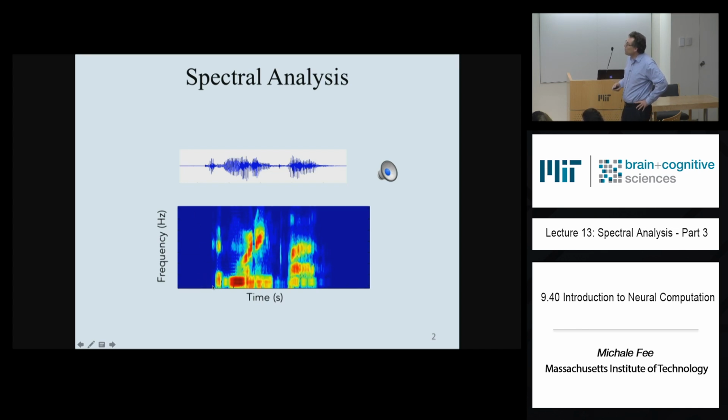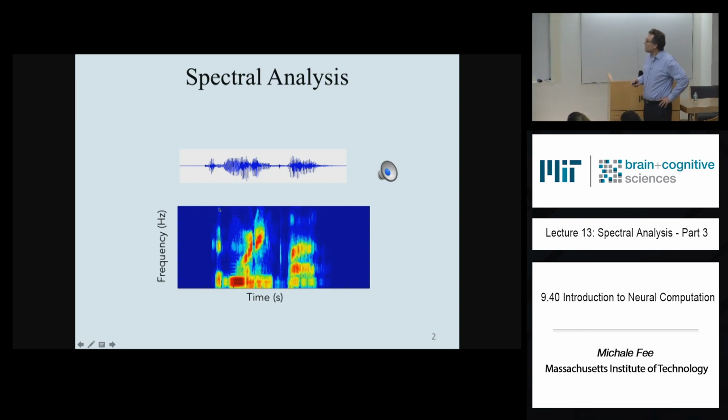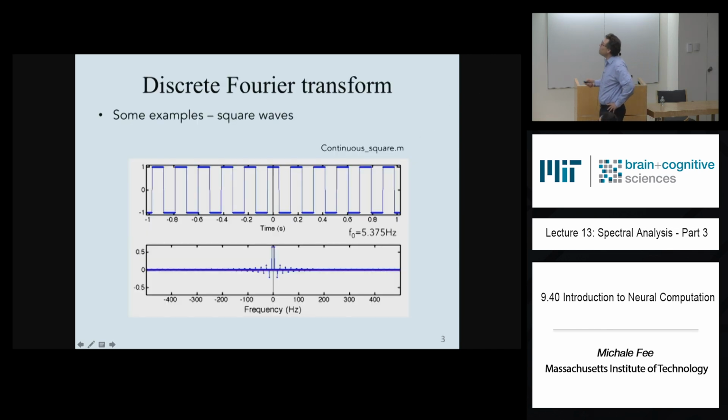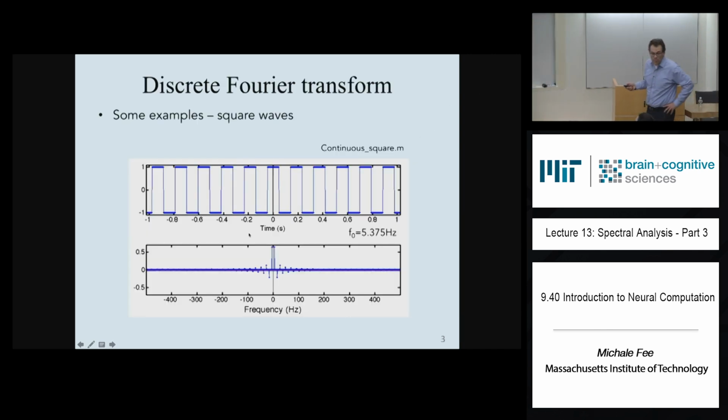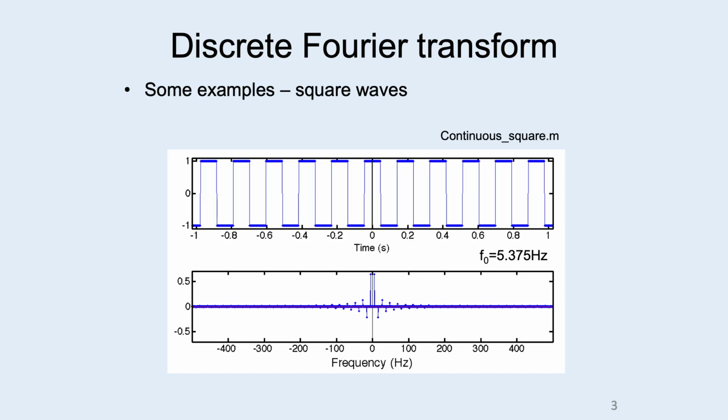You remember we've been learning how to construct the spectrum of a signal, and today we're going to learn how to construct a representation like this called a spectrogram that shows how that spectrum varies over time. As you recall, we have learned how to compute the Fourier transform of a signal. This is one of the signals that we actually started with.